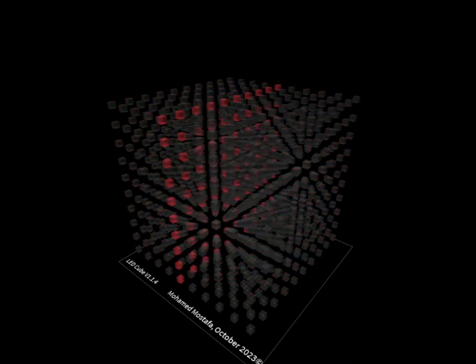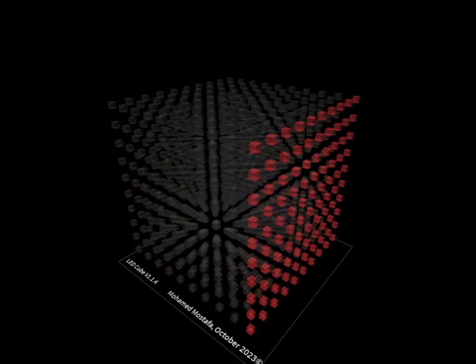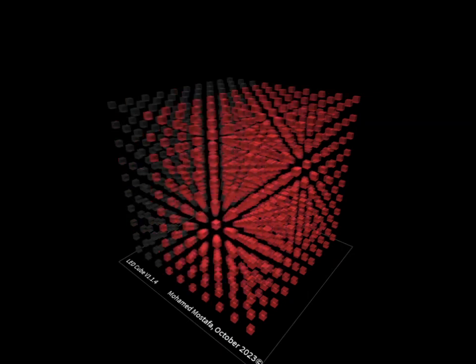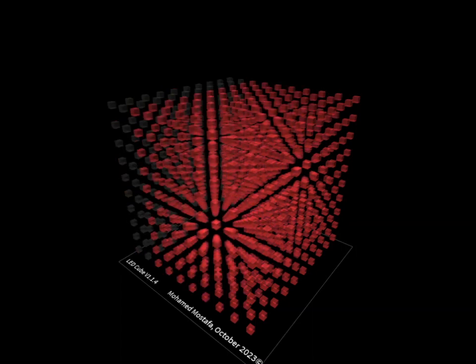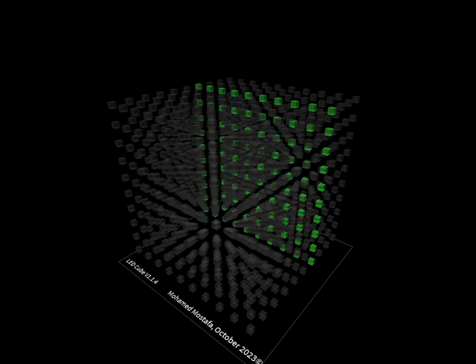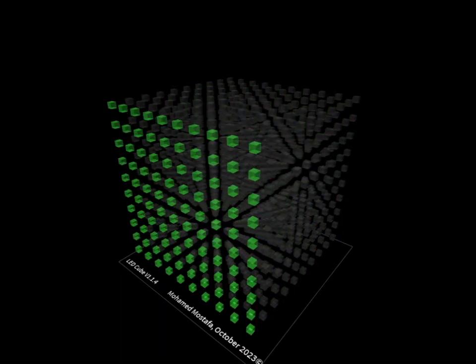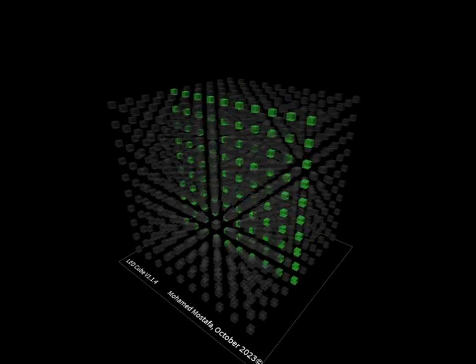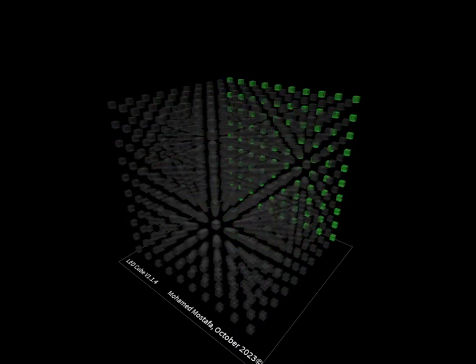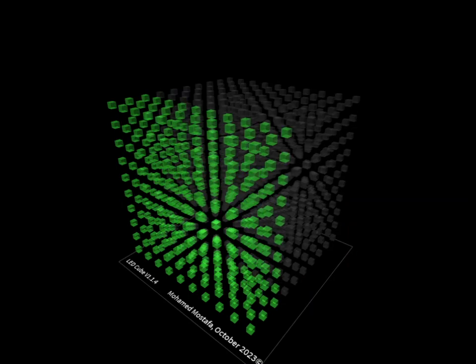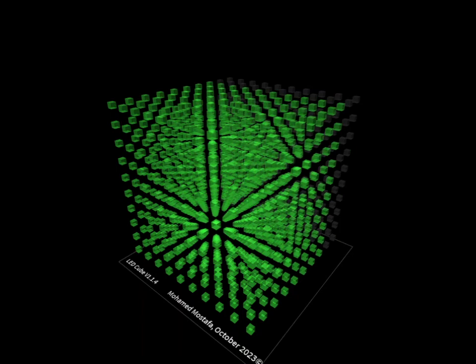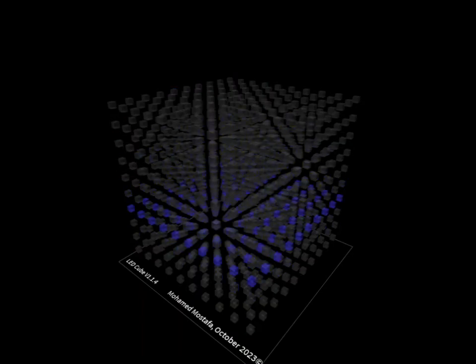To drive a LED cube, you need two sets of I/O ports. One to source all the LED anode columns, and one to sink all the cathode layers. For the anode side of the cube, you'll need X^2 I/O ports, where X^3 is the size of your LED cube. For an 8x8x8, x equals 8, you need 64 I/O ports to drive the LED anodes. You also need 8 I/O ports to drive the cathodes. Keep in mind that the number of I/O ports will increase exponentially. So will the number of LEDs. You can see a list of I/O pin requirements for different cube sizes in Table 1.